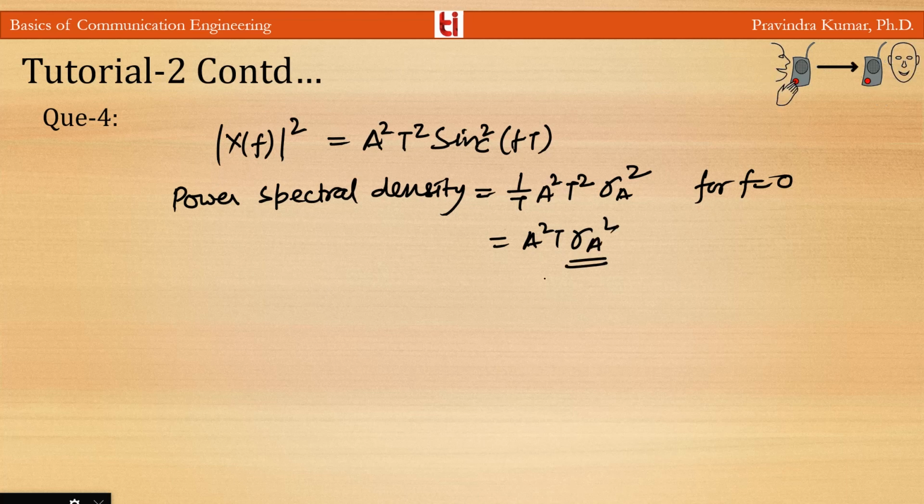The bandwidth of a signal is the width of the frequency band in which 90% of its power is located, or the bandwidth of a non-modulated signal is the smallest possible frequency for which its power spectral density is 0.